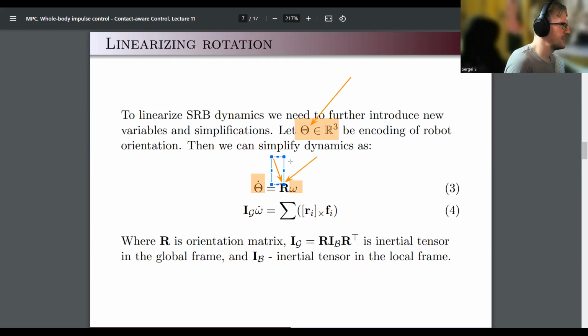It's almost always important to double check. Equation 3 is not a very difficult equation. You can derive it yourself. Maybe the way you defined your orientations, you would have R transposed here. It's very easy to make such a mistake, and then you'll be debugging for a very long time. If you're going to implement it, just rederive it.